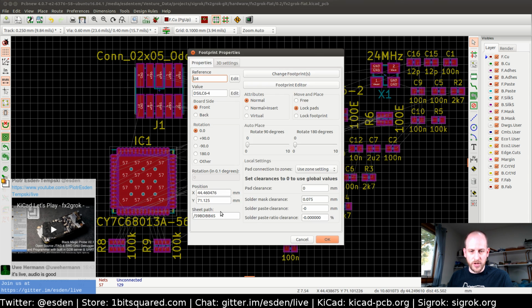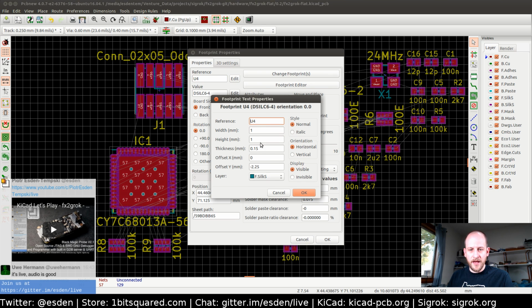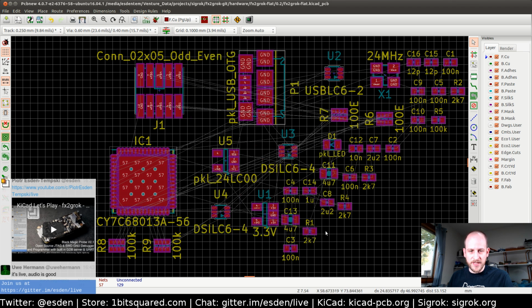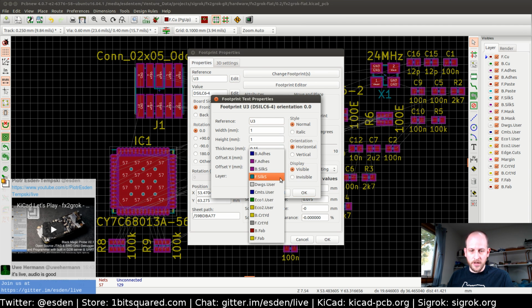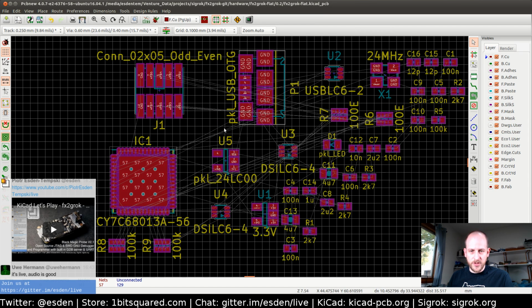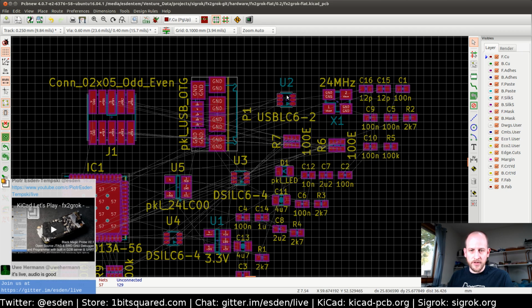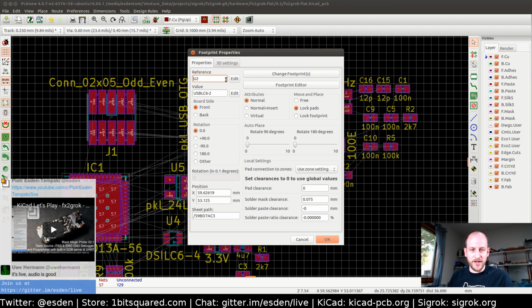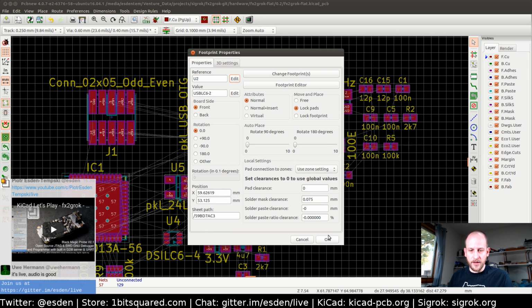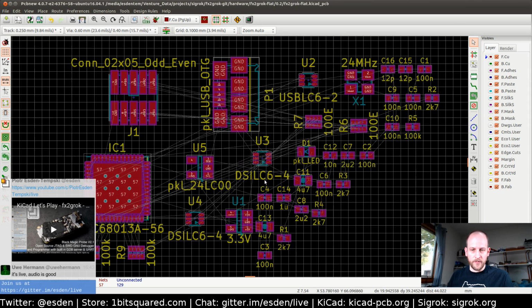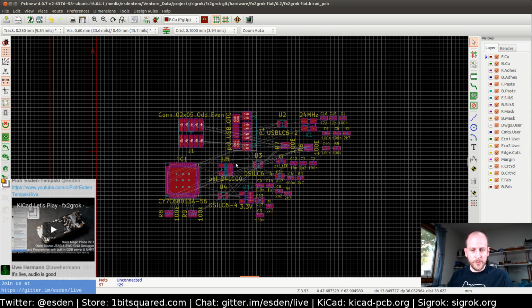This is how I usually use that, because my PCBs are usually so small anyways that there's no space for labels on them. So I'd rather have everything by default be on the fab layer instead of the silk screen layer, that you can then just print out with your printer as a reference for how to populate the board. So let's move that. All right, so that's moved.